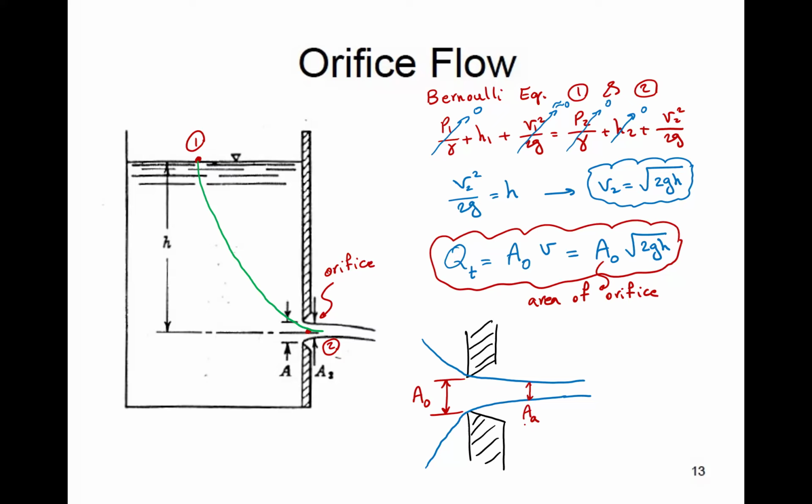And we know why. Whenever you squeeze the flow, the fluid particles need some curvature. They need some space. They need a little bit of gradual change. The flow is not going to turn 90 degrees right away. Just like when you're biking or running, you can't really make a 90-degree turn at one singular point. It's impossible physically. So the flow continues to accelerate. As it accelerates, depth goes down until things balance out, and then the jet thickness doesn't change anymore, right?